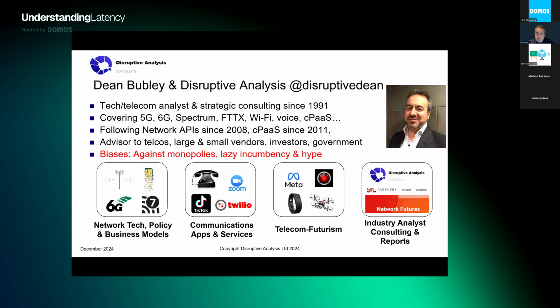A key one that I spend a lot of time thinking about is the indoor versus outdoor split. An important point here is that for wireless networks, the higher the frequency of the radio, the worse it is at going through walls and windows. What that tends to mean is that you use lower frequencies for indoor users, or you need to have some sort of indoor system, whether it's a repeater or what's called a distributed antenna system, or you use Wi-Fi instead, or perhaps even a fixed connection. Whereas outdoors, you've got a whole range of different spectrum. You can bond them together. You can have a certain amount that's reserved for low latency users or high priority users. That's often not the case indoors.